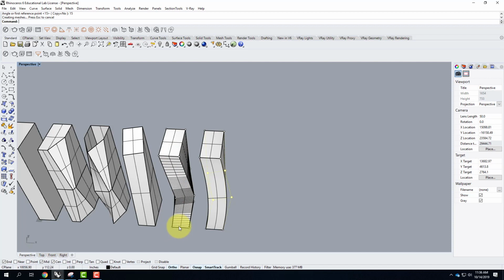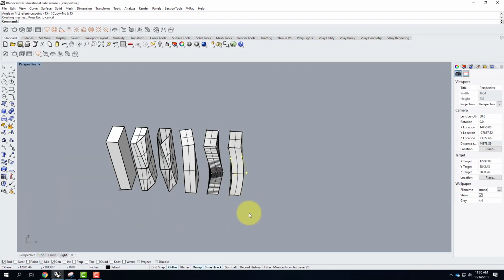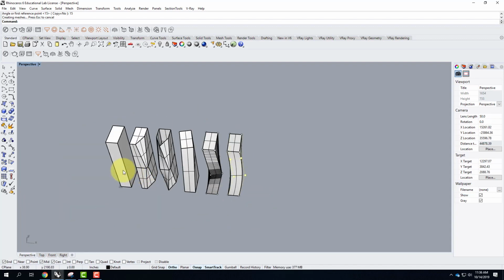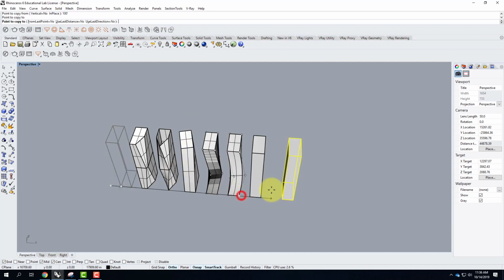The third degree curve, we could switch to the third degree curve, is going to give us results that won't unroll flat. And I'll show you that in a second so you can see it. But generally speaking, we try to stay away from those. So there's our first set there. Let me go ahead and copy this again. And we'll bring this one over.